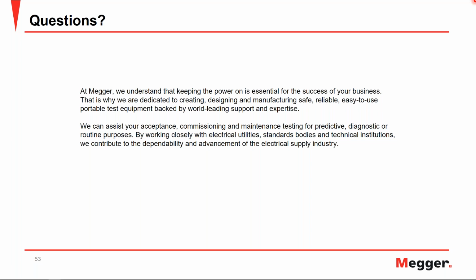All right, thank you. Dinesh, can I perform a PF test on medium and low voltage transformers? So a simple answer to that is yes, you can perform a power factor test on any insulation that you wish. You can take a piece of wire and apply a voltage on that. Obviously, you don't want to exceed the rated voltage of that specimen. So the simple answer is yes, but there is a lot more detail involved behind that.